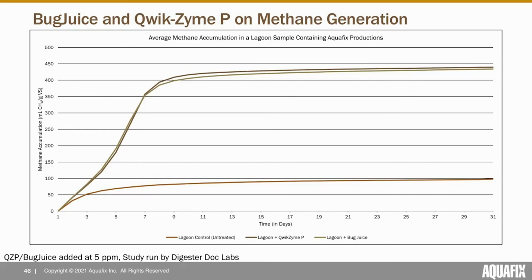A food supplement will create as much methane as you're adding food, and that is basically it. But these increase the availability of substrates, like cellulose from manure, or proteins from dairy wastewater. If you start to metabolize those more effectively and you're limited in your system on certain nutrients, like this system may have been limited on ammonium and free amino acids, Quicks IMP appeared to help out with biogas generation fairly dramatically.